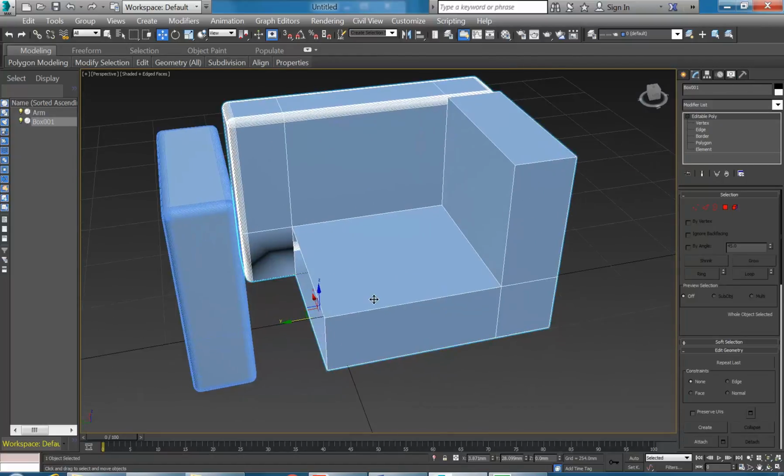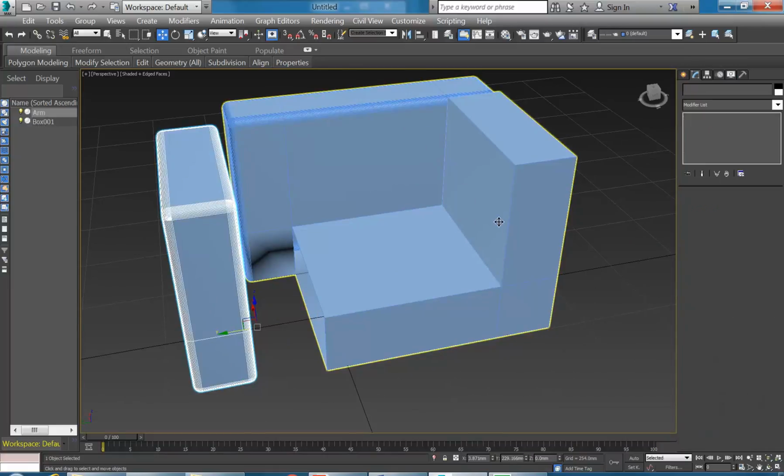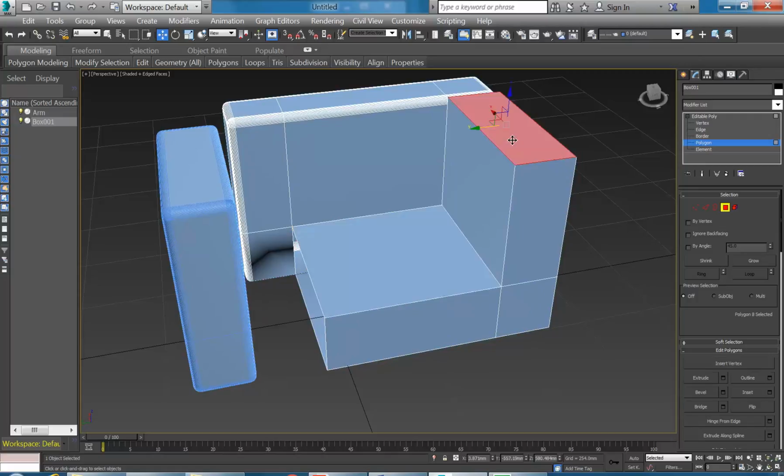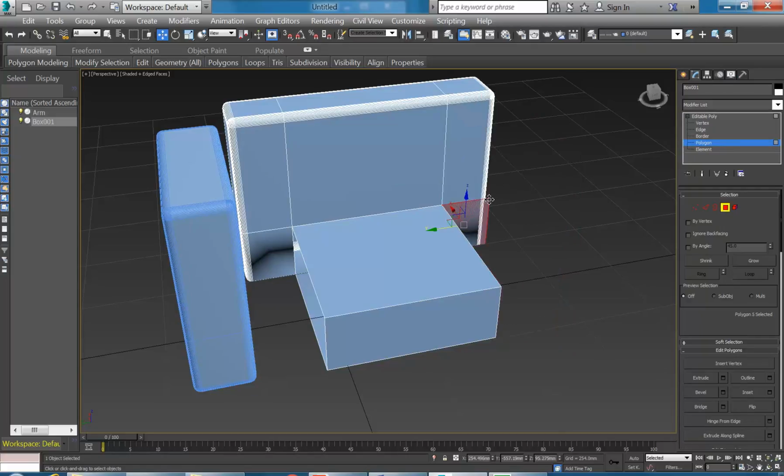And so then the cushion, I could do the same thing. The arm, I can copy across. So there I might decide, well, I don't need those faces anymore, so I can just easily delete those. Not a problem. Holding down control. So there's a lot of flexibility when you're modelling this way.